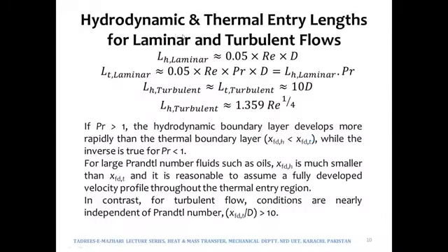Now summarizing the things, the hydrodynamic entry length in laminar flow is 0.05 times Reynolds number times d, whereas the thermal, the XFD meaning fully developed thermal length, in case of laminar flow is 0.05 times Reynolds number times d times Prandtl number. So we can write it in this form.